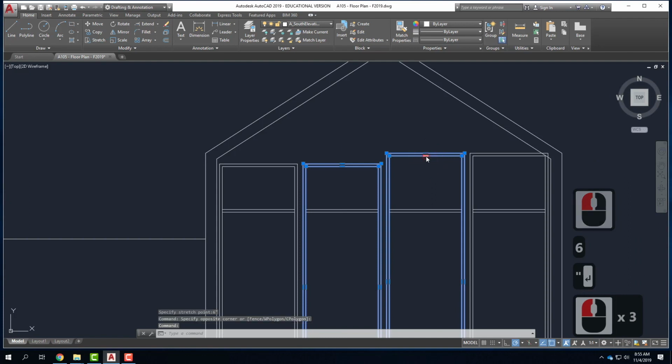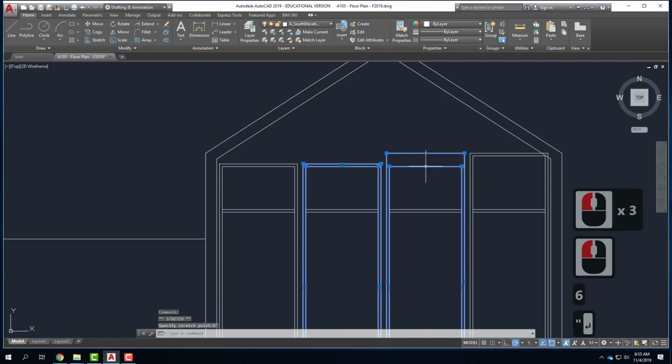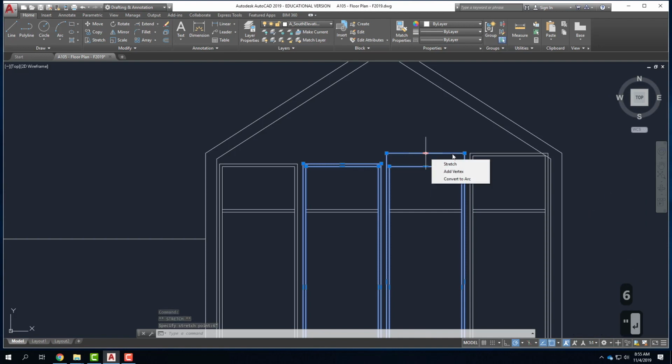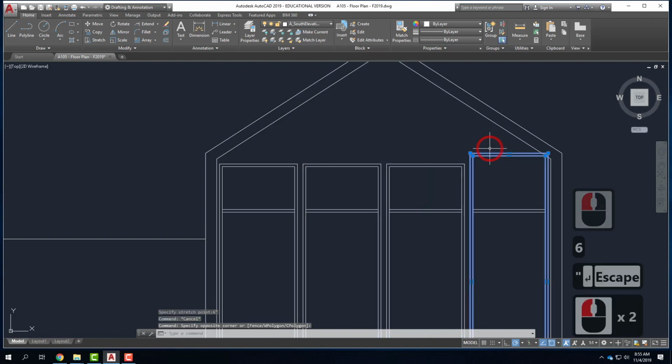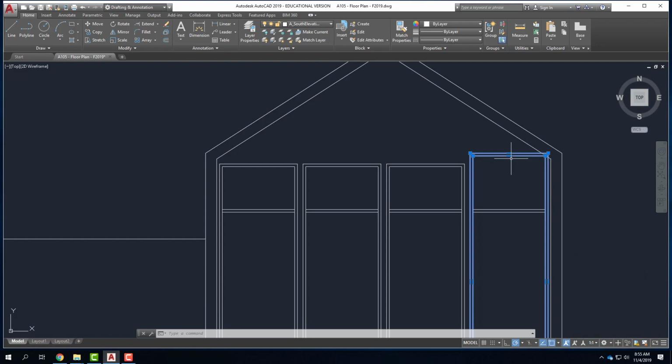How come, when you're offsetting the roof, you offset it inside instead of outside? I could have done it outside. Yeah, you can absolutely do that. I'm not being perfectly technical about how you would determine where the roof is. It has to do with the wall and the plates and what the bird's mouth looks like. There's a lot of technical detail to the section that we could go into, but it's just not relevant for you guys at this point. So I'm doing kind of basic. Just go from the corners and come up. Usually you would have to add, and the roof would be taller than where your ceiling height would be.